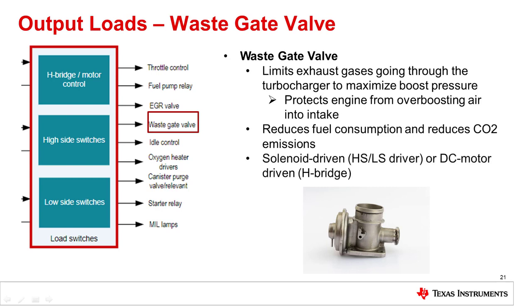The wastegate valve is conventionally driven by a solenoid, but can be motorized using a butterfly valve design with a DC motor. Therefore, a high side or low side driver, or H-bridge, can be used for the wastegate.